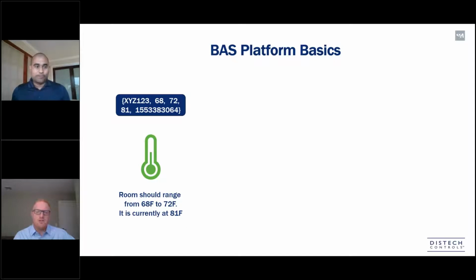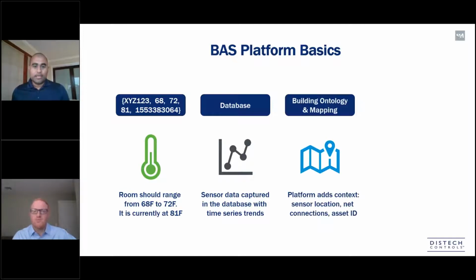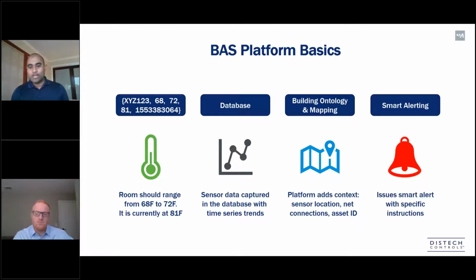It's important for any BAS platform to have a good data aggregator where it can take in sensor data from different sources. It needs to be able to correlate different data sets and have timestamps associated with them. Then it's important to add context to the data by connecting the dots with locations, nomenclatures, and algorithms, and ultimately make all of this actionable by issuing alerts or recommendations.